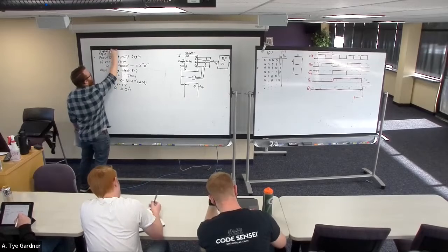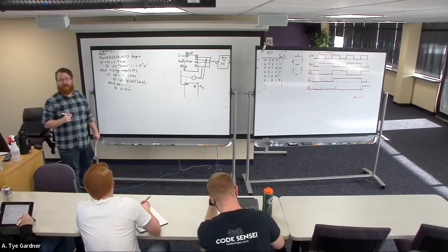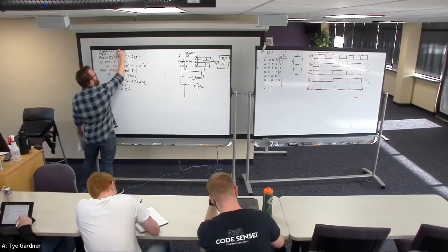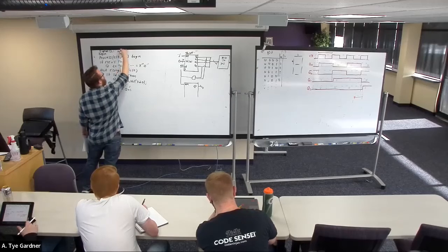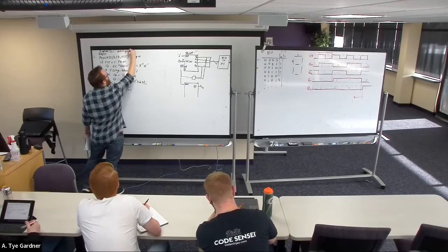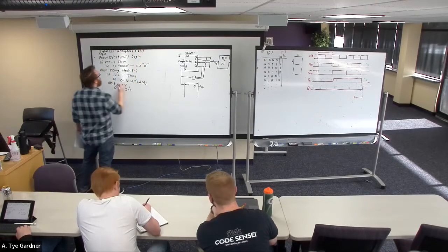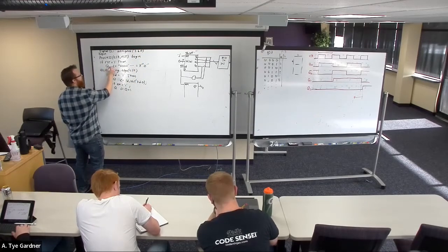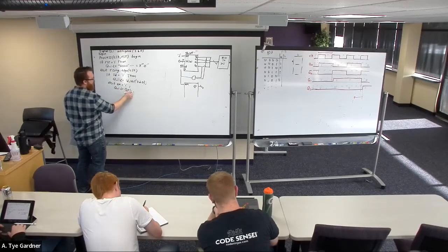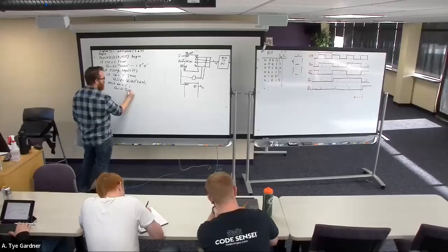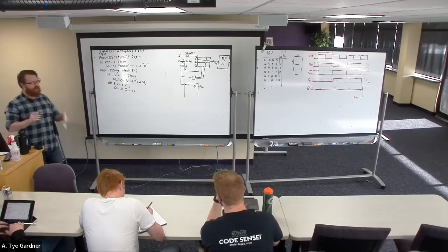And I'm going to call it QI for integer. I'm actually just going to make this an integer. The way that I do that is I say, actually, let's do unsigned. It's a little bit easier to convert unsigned, and it's also allowed to add one. Unsigned 3 down to 0. And now I'm going to convert this to QI, this to QI, and this to QI, and this one to QI plus 1. See why I left those spaces before and pointed it out so I could do this conversion.